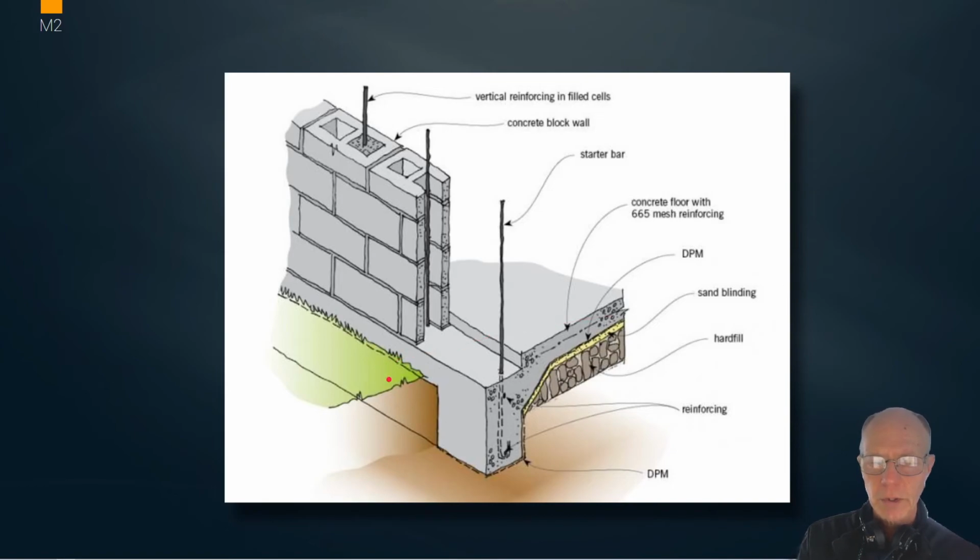Here's kind of what happens down at the grade level at details. So we'll be pouring a floor. We're not going to specify this kind of level of a notch in order to include the concrete block wall. But typically they have rebar going through them, reinforcement bar, that ties them together to give them vertical strength that way. And they sometimes have a mesh that goes between the mortar line in order to create strength in the transverse direction.